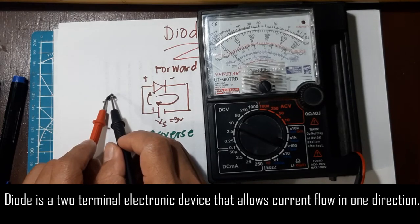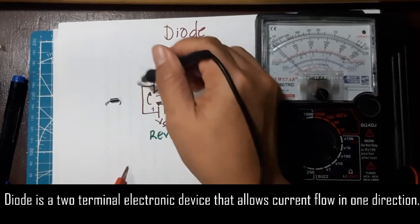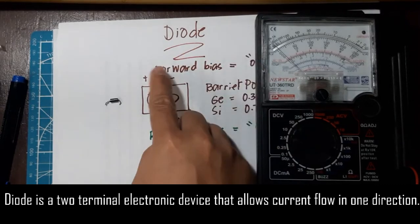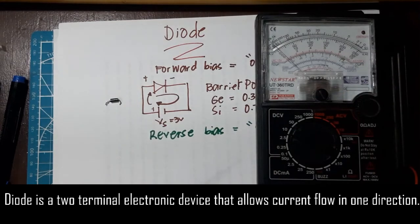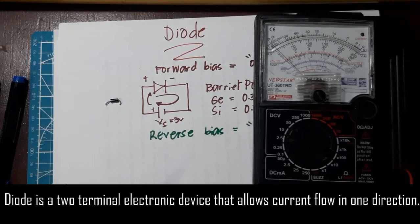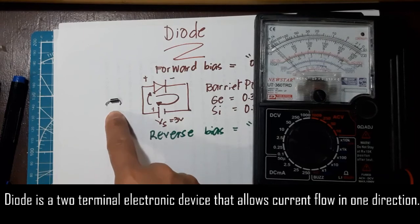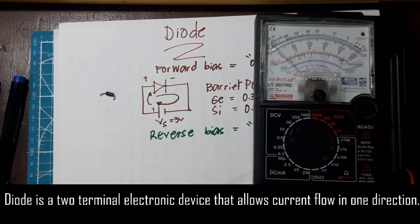See? So you have two states, forward bias and reverse bias, in order to conclude that your diode is in good condition. Otherwise, if it's forward bias and the other one is also forward bias, we can conclude short circuit. If it's reverse bias, which means high resistance, both end to end, reverse bias, and the other one is also reverse bias, we can say that our diode is open circuit. So it's damaged already. Okay, so you need to replace your diode if that is the case.